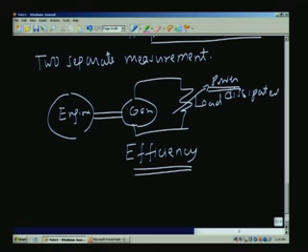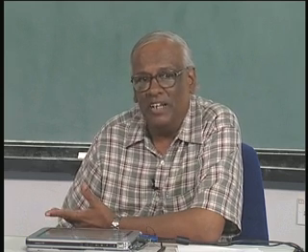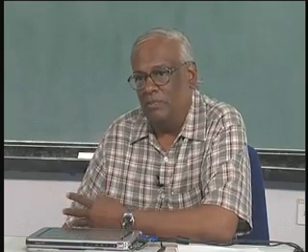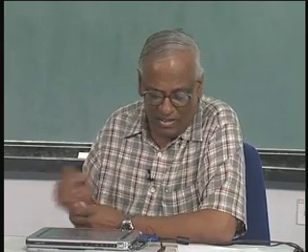Or for example, if an engine is running a water pump, and if we can measure the output of the pump in terms of the flow rate or the mass flow rate of the water, and we know the head through which it is being pumped, there is another way of finding out what is the power output. So, that also gives you power output. Of course, there again the same problem will come, what is the pump efficiency and then what are the losses in the intervening parts, for example lubricant losses due to friction and so on. So, those are the problems which will come into the picture, but for a rough estimate it is possible to do that, and in many cases that may be sufficient.